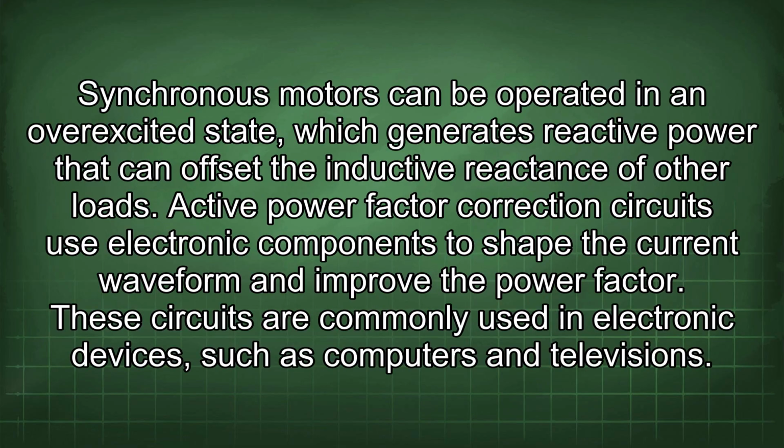Synchronous motors can be operated in an overexcited state, which generates reactive power that can offset the inductive reactance of other loads. Active power factor correction circuits use electronic components to shape the current waveform and improve the power factor. These circuits are commonly used in electronic devices, such as computers and televisions.